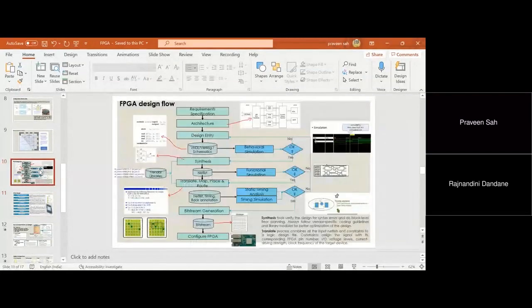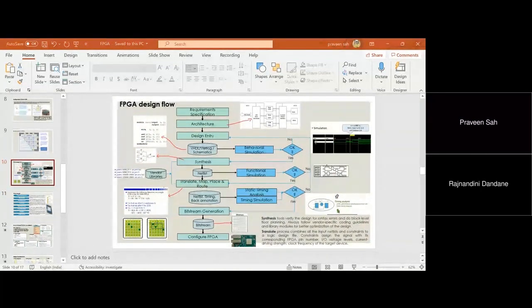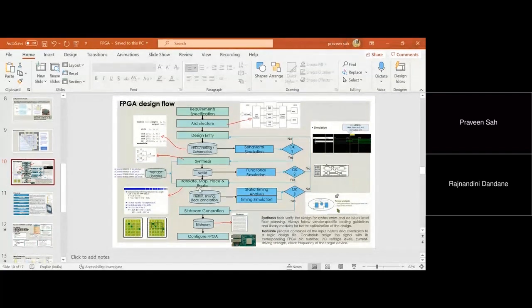Yes. Just one question on the last part, that bitstream, where you expect a series of ones and zeros to be created. Does it give you the binary file in the end, which you can flash into the firmware? True. Based on whatever tools you are using, like Vivado tools, it generates some kind of MCS format. It is nothing but a bitstream file, a binary file.